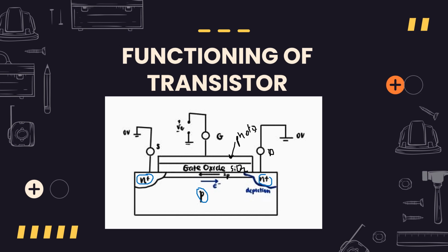This photoresist will have the pattern designed through the photolithography, as well as the source and the drain, which will be covered by the deposited metal. So initially, we have the p-doped and n-doped regions, and we have here this area separating them, which is called the depletion area. That area basically acts as a barrier between both types of semiconductors.